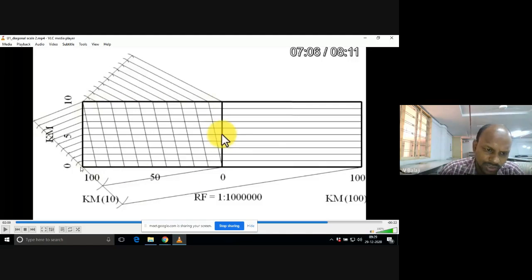Again, on the left hand side, you can observe here there is an inclined line drawn. Okay, don't confuse. Here initially we have done two parts with the line division method. At the top, we have divided this first part again into 10 parts with the line division method. Okay, here now again we are doing the vertical height again into 10 parts. So the last arc we have to join to the height of this box.